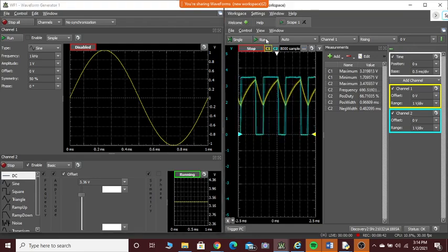Can you see what is the maximum of C1? Is it almost the same as the external voltage, this one? And is this almost half of that? Can you see this negativity is almost the same as the previous case, 0.47? The reason it doesn't change is that negativity is independent of the control voltage. It only depends on R2 and C.